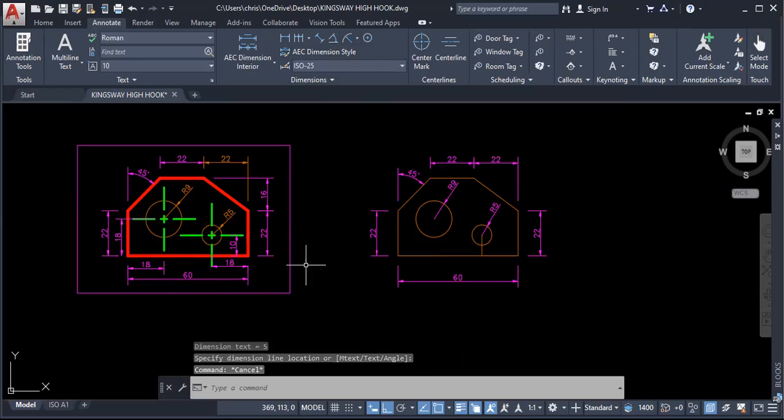Now I need to establish my 18 millimeters from that point, or the location of the center relative to a point here. So I'm going to align. I click here, then I move towards the center and I click there, and I now have that. It's space bar to reactivate. I click here and I click there, and I now have 18. Hit space bar to reactivate.